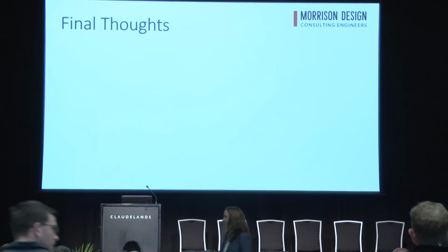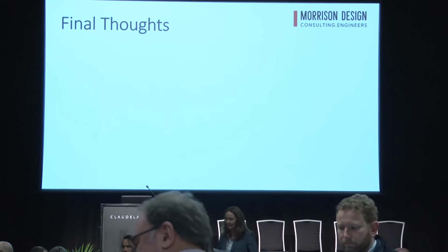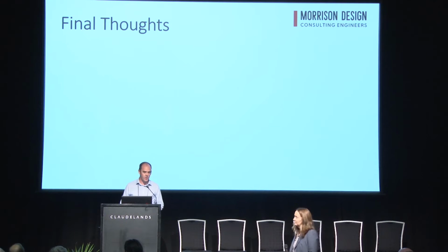In the design of scaffolding, what return period wind speed do you use? Sorry, I thought I'd gotten off easy. Just stay there. It's a 1 in 100 year event. It doesn't give you a whole lot of down rating from the full building load. The justification for that is from 1170. So 1170 has a return period for scaffold and construction equipment.